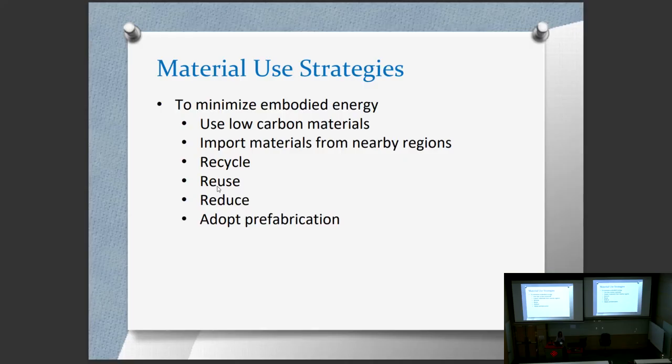So reuse the materials and products or the elements from the existing building. Or there is an approach called deconstruction. Deconstruction is that when you tear down the building, you carefully and partially dismantle the existing building so that you can recover the building materials, and these materials can be reused elsewhere, in other new buildings. And reduce, so how to reduce the building material?